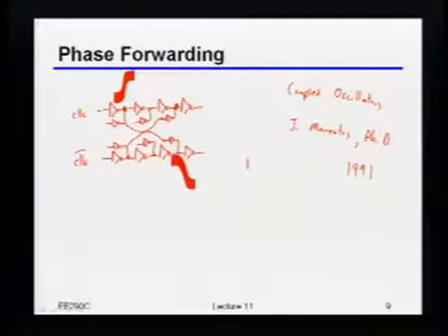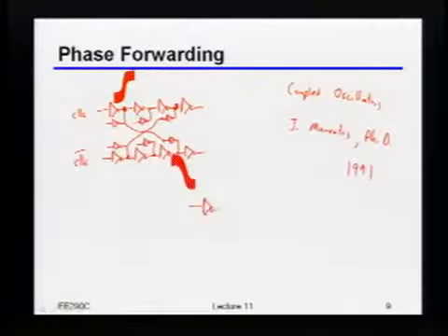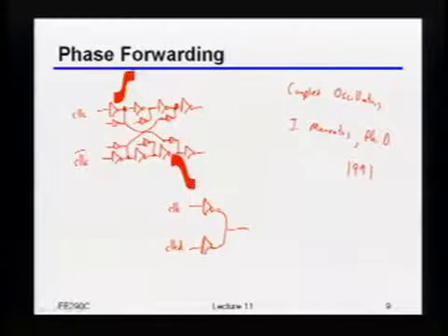Does that make sense? Or, by the way, this is more generally how you do what's called phase interpolation. Okay, so more generally, let's say that you do want something that has a variable delay or a variable clock phase. Well, what you can do is take 2 clocks, for example, some clock and some delayed version of the clock, right? Just feed them into 2 inverters. If you short their outputs together, then you'll get something whose delay is somewhere in between the delay of the 2 inputs, okay?